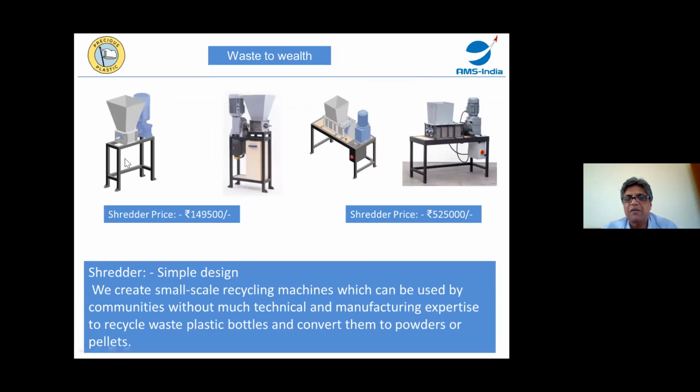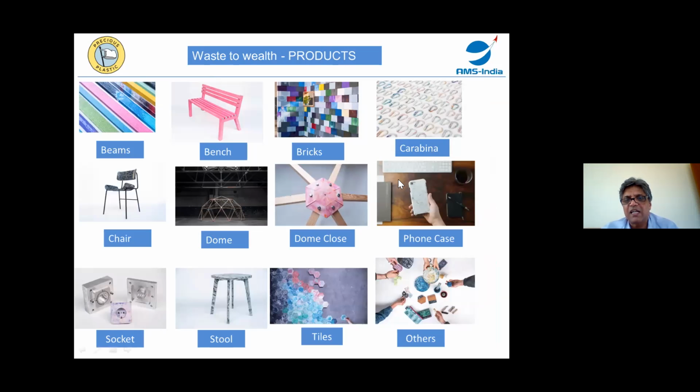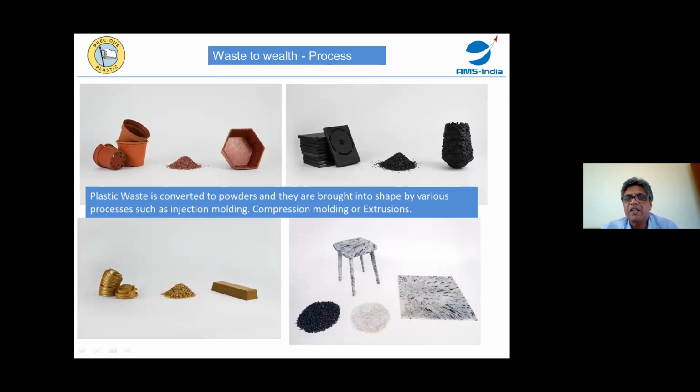First, you shred the plastic here. See this. You can see the colors out here, all this black and white. All this, you can see there are different colors. What is happening is you have a bottle coming out of Harpic, and then you have a bottle coming out of PETG. You have water bottles, etc. You mix all the plastic powder together, put it in a sheet press. You get this, the mixed colors.